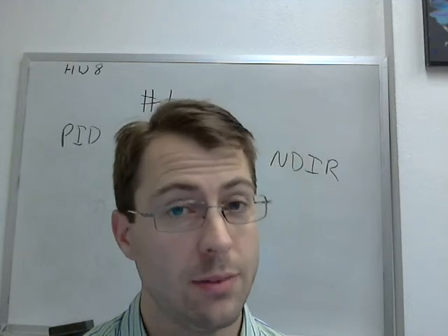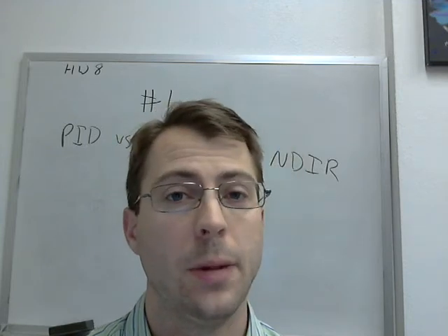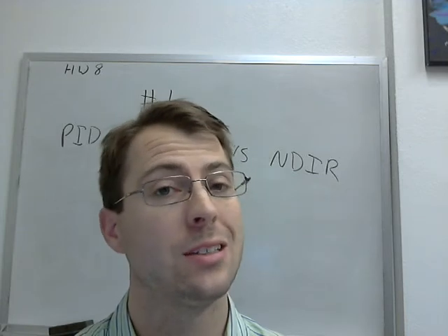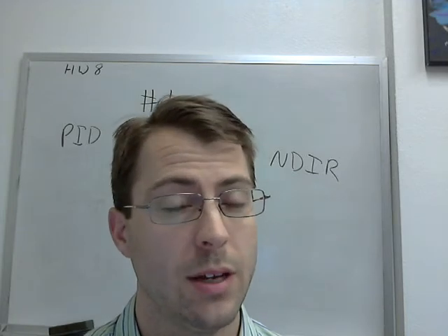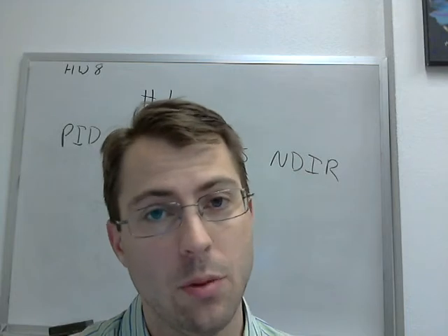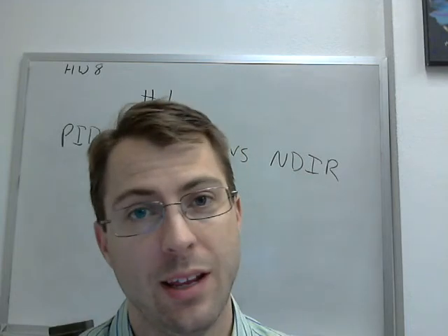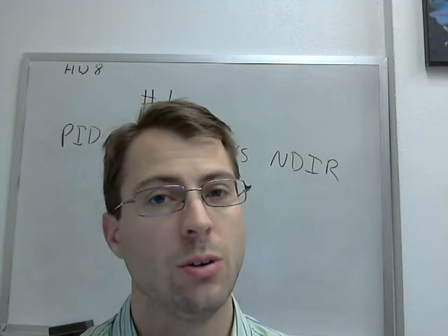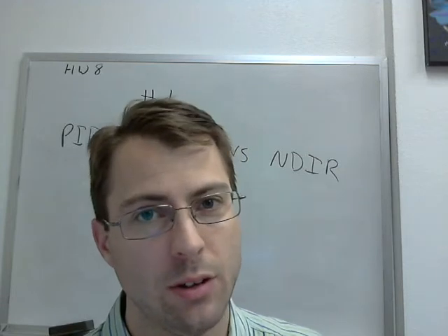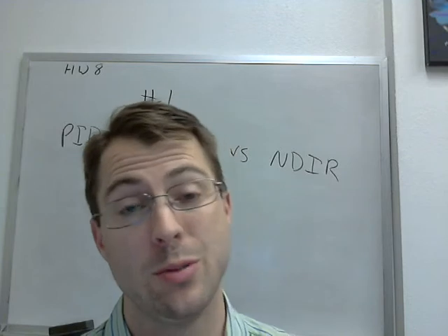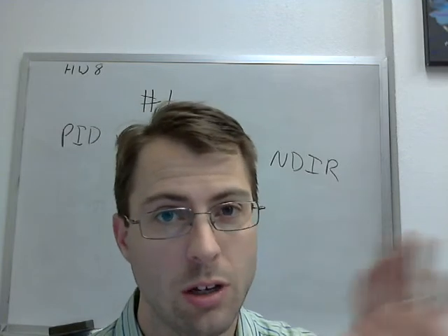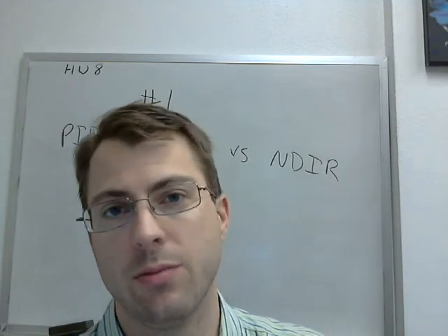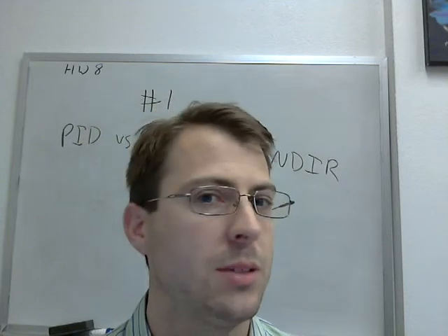An FID would definitely pick up methane, but what if you've got a high concentration of methane in a small little environment? You stick that FID probe down in there, you pull that explosive environment into your detector, perhaps you have a little explosion in your detector, perhaps you ignite that larger microenvironment and you have a little flash and cause an upset condition.